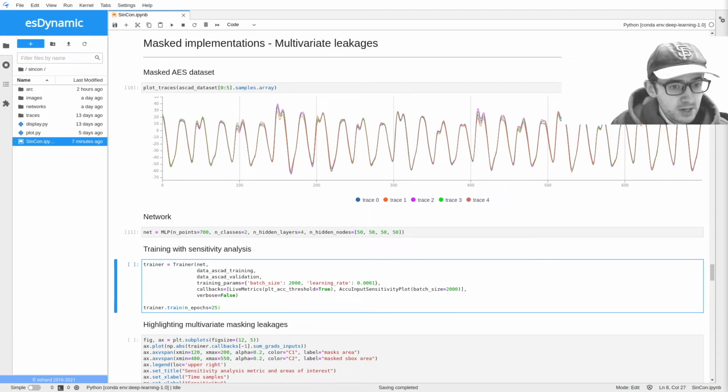The simplest example of that is when a sensitive data is split into two shares, a mask and a masked value. In this case, if we want to perform an attack targeting this protected value, what needs to be done is to identify and combine the leakage of the first share with the leakage of the second share. This is what we call a second order attack. It's usually quite challenging to do because the two leakages must be identified first, and then the leakages must be combined together before the attack is performed.